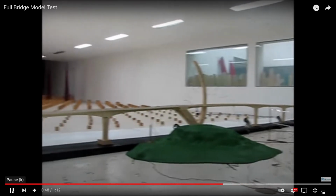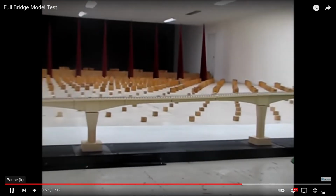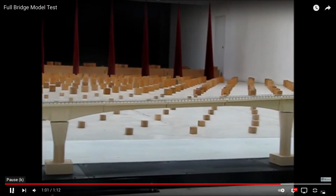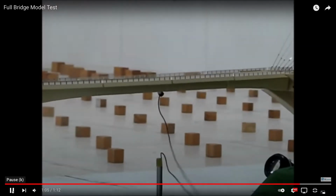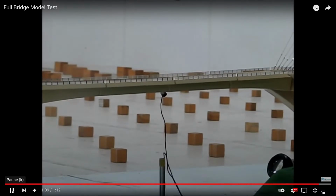For Tacoma Narrows, it's not so much that it's a high wind, but it's a constant wind at a particular frequency. And just like a guitar string that has a resonant frequency, that's the sound you hear, a structure would also have resonant frequencies, a major one and minor ones, at which if you supply an excitation at that particular frequency, then you put it into resonance.